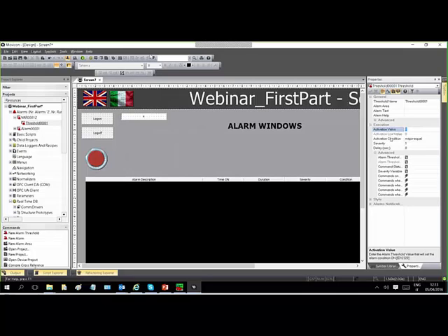I missed showing that I just inserted variable 17, that is a word. So it is 16 bits in this case. The purpose is to enable a different alarm for each bit. Customers use this to pack the alarms, exchange a word and generate 16 bits, basing it on only one variable, this word.